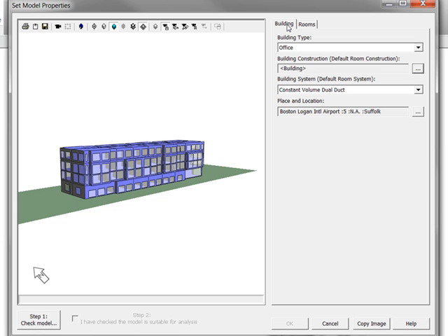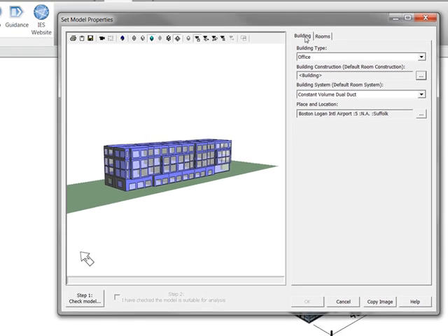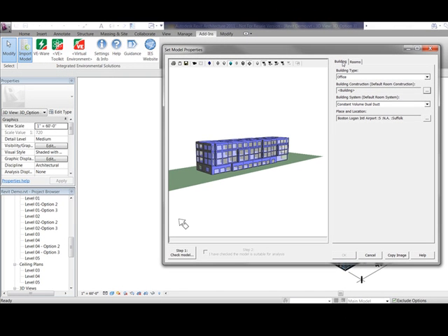So create a baseline and change one thing, whether you're changing form and seeing the effect or changing shading and seeing the effect. That's the way to start to understand what has the biggest effect on my model.